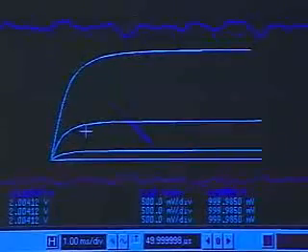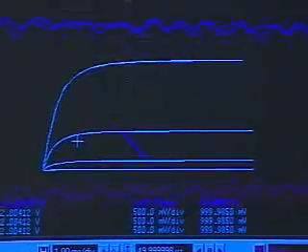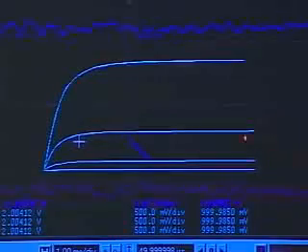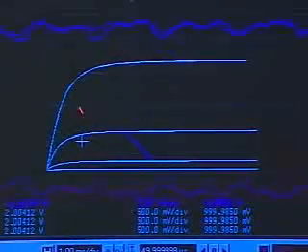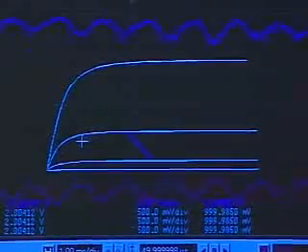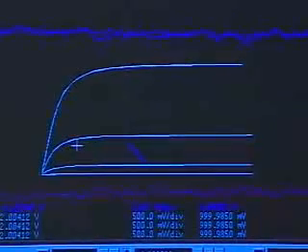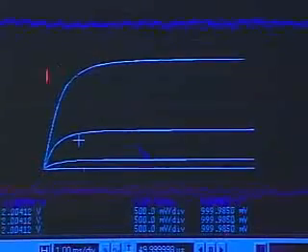So notice that as I went up here, the volume kept increasing, because the gain kept increasing. But as I got into the triode region, I began to lose my gain because, remember, the amplifier doesn't have gain in the triode region, and the MOSFET in its triode region, and we also get a bunch of distortion out there. Okay?